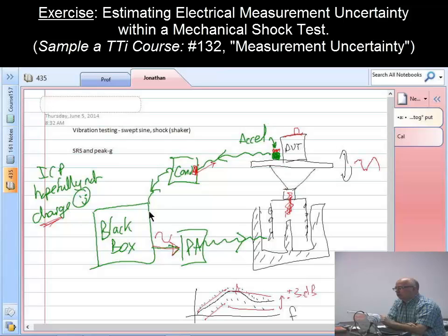Yeah. And typically, if you're doing a swept sine, where you put a frequency out and just slowly increase it, because it's digitally generated inside here, and it goes analog at this stage and comes back and is digital at this stage, we know exactly how long that time period is, so it can match the filter to be exactly that. If you don't use a filter at all, you get side lobes, because if you think of a Fourier analysis, that tends to give you fairly high side lobes. We try and play with windowing to reduce those. But if you're doing a swept sine, the black box typically has a very high matched filter with huge suppression, because we know exactly the length of the time.